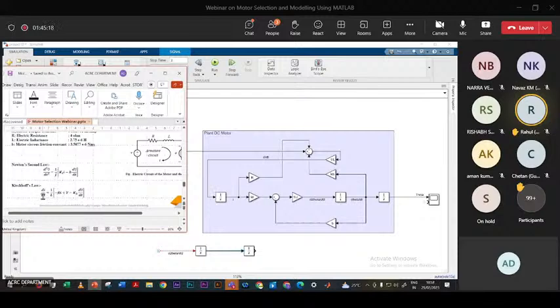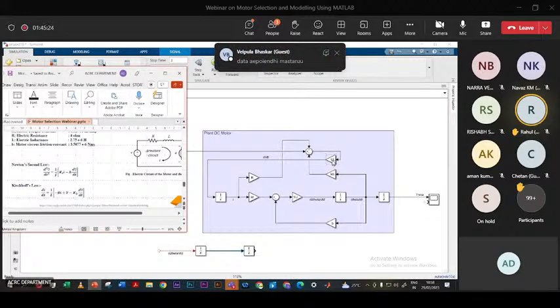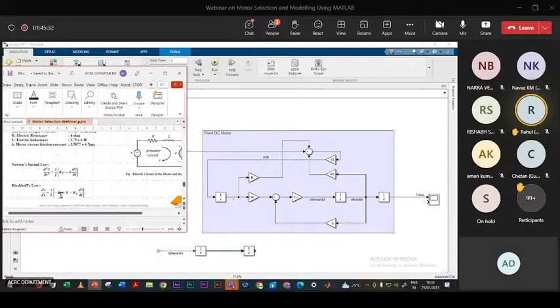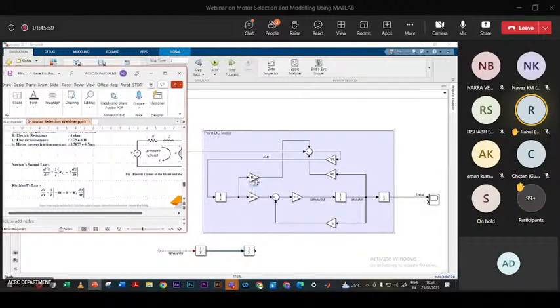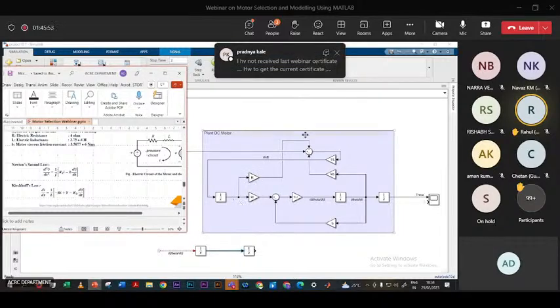So here I have the di by dt, which is equal to the IL times 1 by L. I have used the gain 1 by L here, so it finally comes to di by dt. Then what I require here is a summation, where I want 2 subtractive and 1 additive. So I used a summer here, with addition, subtraction, subtraction. For the first one I used r into I, so I got here I, and I use the gain r here, and then add it to the summer.